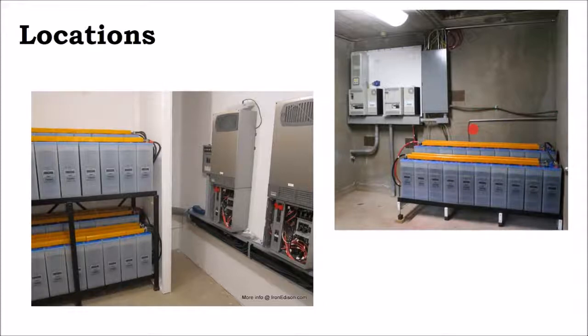Well, then the solar guy might say, oh, but it's a DC circuit, and DC circuits have to be enclosed in metal, and that's why we did an EMT conduit. And the inspector might come back and say, well, that may be the case, but metal conduit still can't be in a battery room. So what you need is a metal conduit with a PVC coating around it, like that flexible metal conduit, depending on how tough your inspection is.